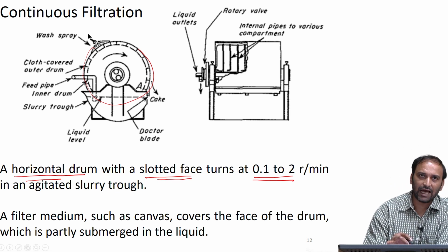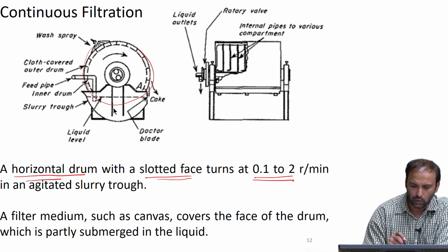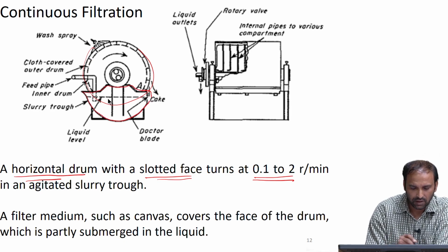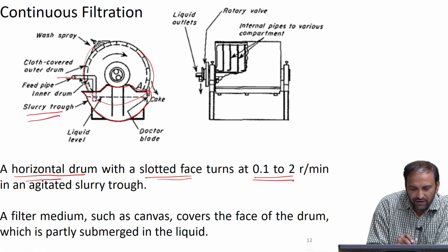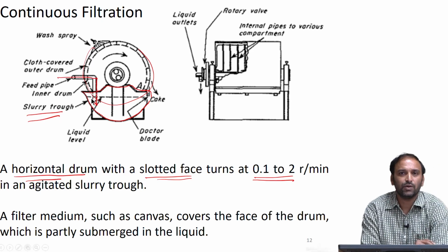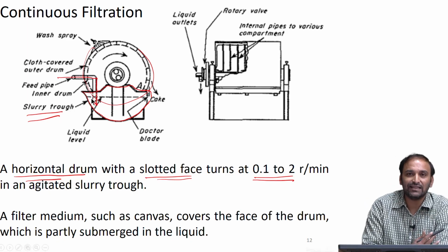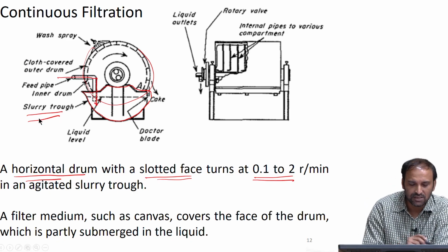If you look at the diagram carefully, this particular drum is partially immersed in a slurry trough, and there is a feed that helps us feed the slurry that needs to be filtered into the slurry trough.